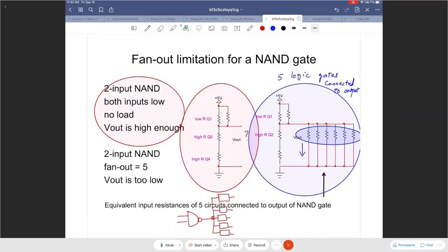It goes down. And when it goes down, what is going to happen to the voltage? When the resistance is going to go down, voltage proportionally is going to go down, right? Again, the same voltage divider. V out will go down. Now, V out goes down. The problem could be V out is too low.